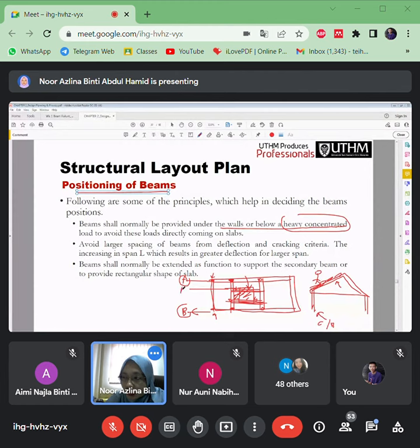Let's say there will be A1 here, there will be A2 here. But the grid line from the architect maintain here AB. We propose the additional grid line to show that there will be other structure that need to be provided in this line, in order to support the water tank and so on.